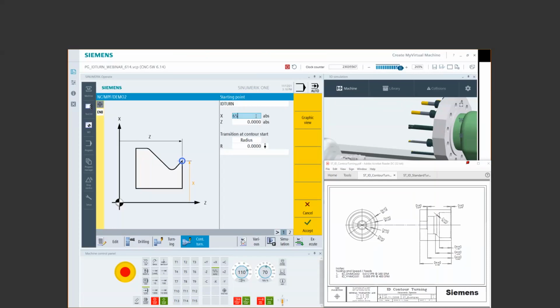Quick little trick. If you're working from a part print that has metric values and you're in an inch program, if you type a quick I next to the number, it'll convert it for you. Look how cool that is. Same thing, I go 2.5 M, it'll convert it to a metric value. So it's independent of whatever unit of measure the system is, but it's nice because now I'm not getting rounding error. It's going to round it for me. So it's the number and then the I for what unit of measure I want it to convert to.